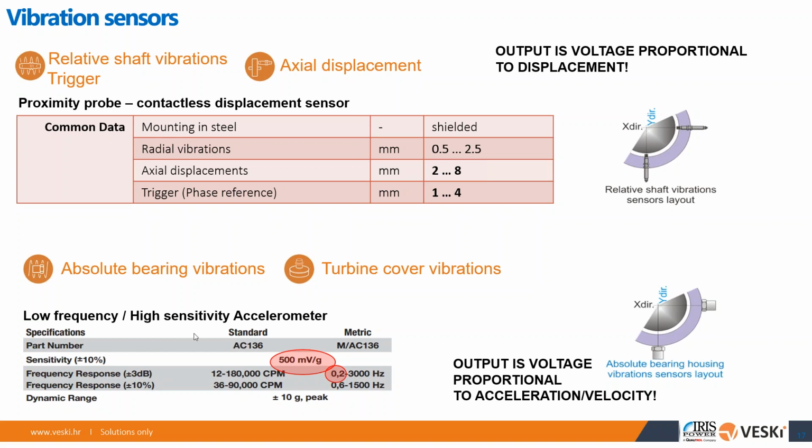And for these low frequency wobblings, it has to be as low as it can go. So basically 0.1, 0.2 is what you can find now on the market. The upper frequency doesn't really matter. It's the low frequency: as low as it can go, and as high as it can go with the sensitivity. And it doesn't matter which brand it is. They're all pretty much the same. They're commodity products. There are better and worse, of course.